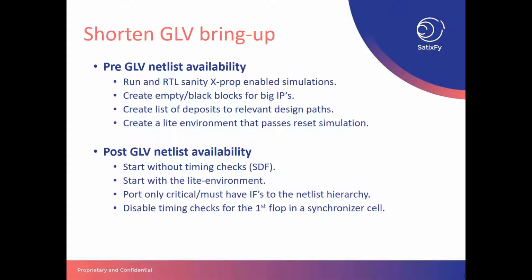And obviously, you would like to disable the timing check on the first flop in the synchronizer cell, as these flops have a large probability of violating and creating X's that will fail your simulation.